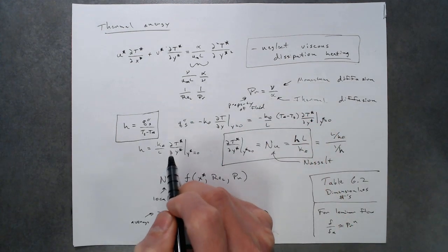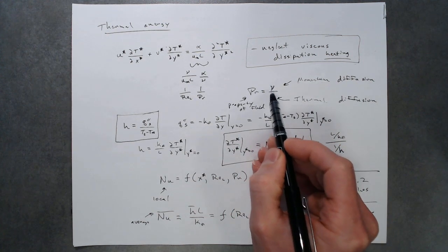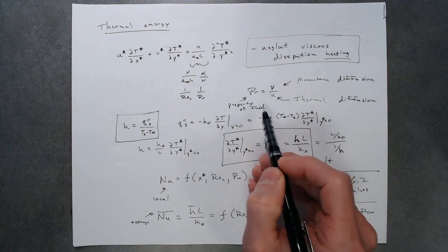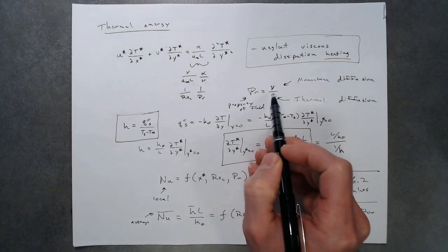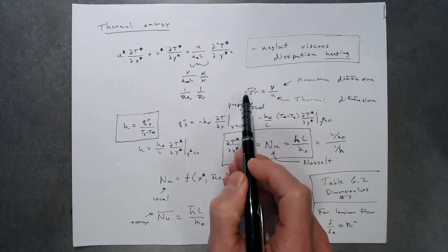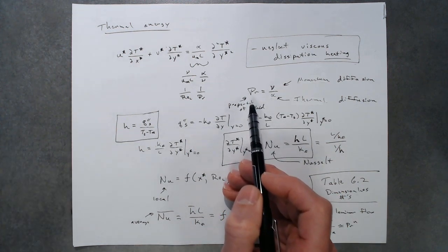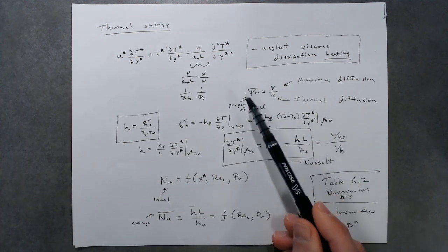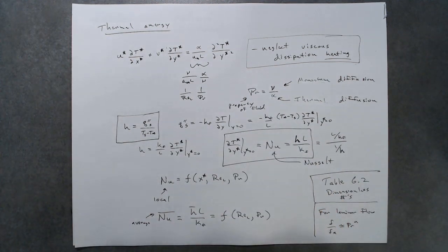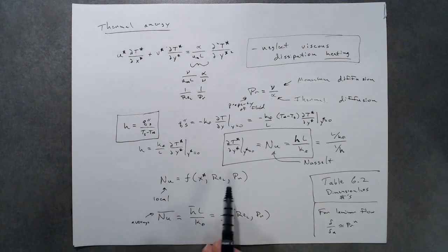Now, it does depend on the temperature, as each of these properties depend on temperature, but the momentum diffusivity, the kinematic viscosity, and the thermal diffusivity are both properties of a fluid that I can look up at a specific temperature. So the Prandtl number depends only on the fluid composition and essentially the temperature. The Prandtl number can also be affected by pressure for a gas, though for a liquid we would generally consider them to be incompressible.